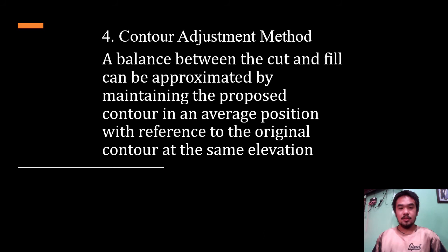The last method is the contour adjustment method. A balance between the cut and fill can be approximated by maintaining the proposed contour in an average position with reference to the original contour at the same elevation.